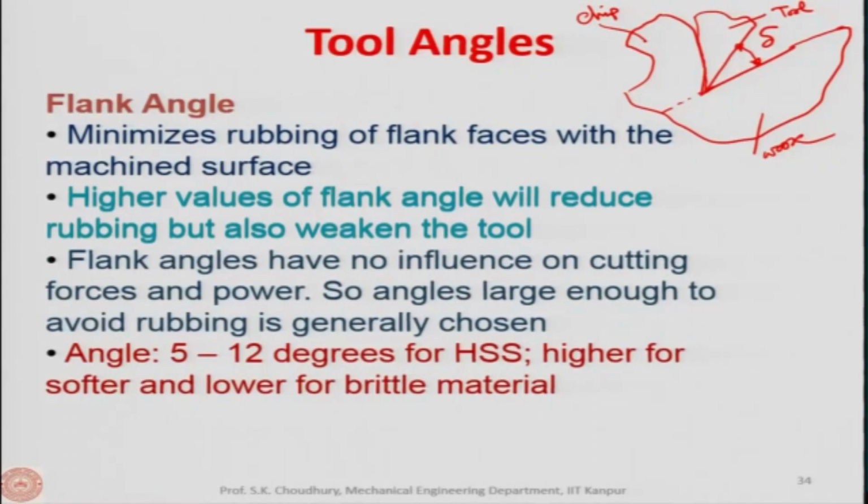Now, higher values of flank angle will reduce rubbing, but also weaken the tool, because if the flank angle is increasing, the cutting angle is decreasing and the tool is becoming weaker. Less material will be available to conduct the heat, and there will be thermal deformation.